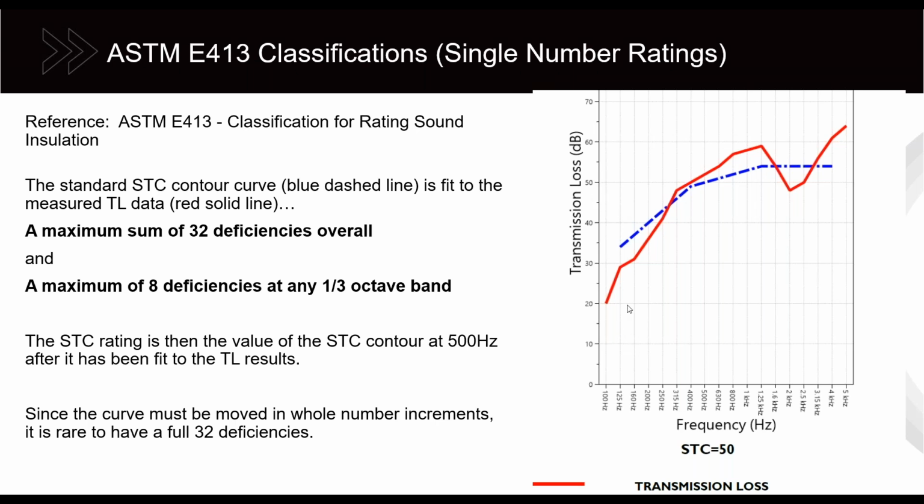This is also why nobody should run a subwoofer in a multifamily housing situation, because even with this wall here, which barely passes building code requirements, at 80 hertz or 60 hertz, which a subwoofer could produce, you have very low transmission loss, which means that subwoofer is almost as loud for the person in the next room as it is for the person in the room listening to it.